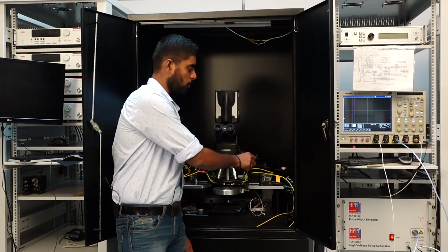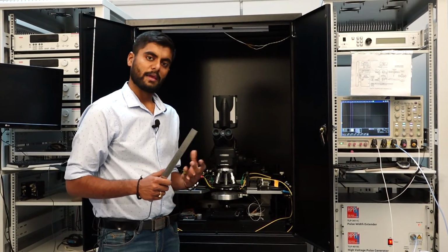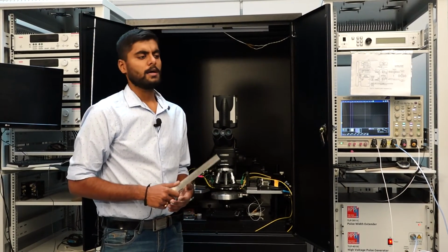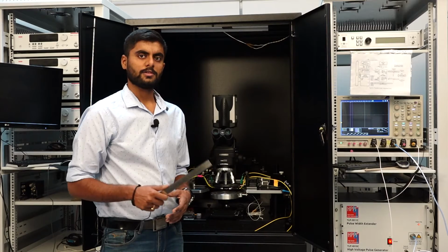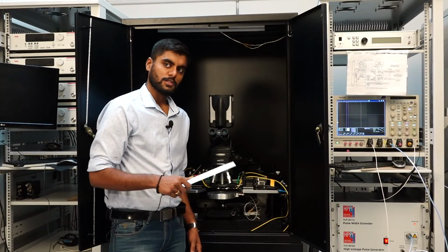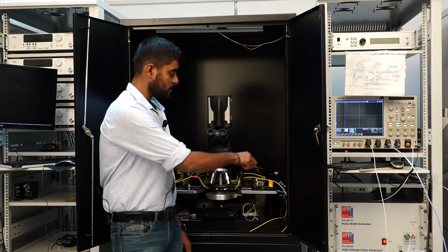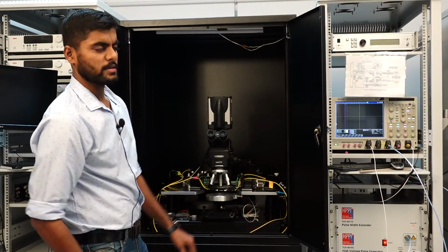These hairs are then called probe arms. So whenever you have your device under test, you have to make an electrical contact with it as well, right? You have to make electrical contact with the source, drain and the gate contacts. So these probe arms are then used to make the contact with the device under test through these wires, through different assembly of the components that you are going to use.